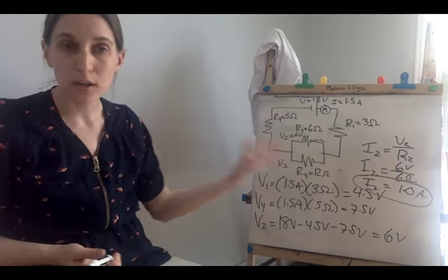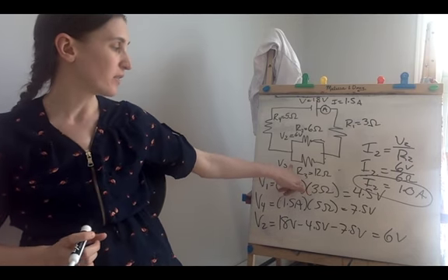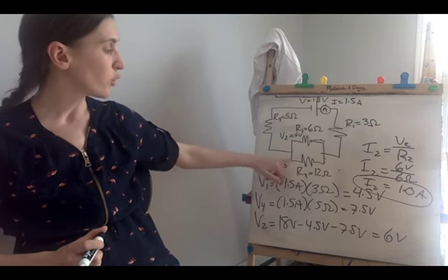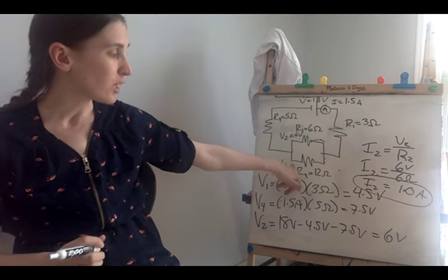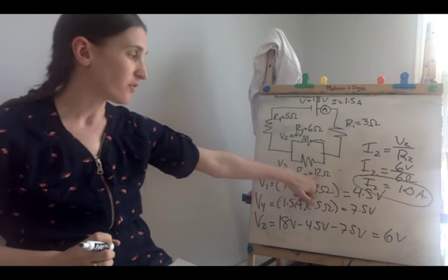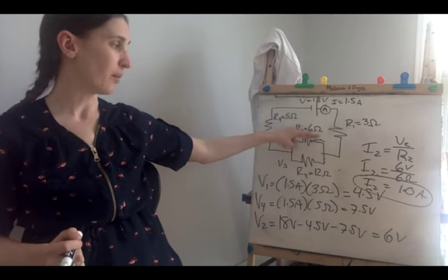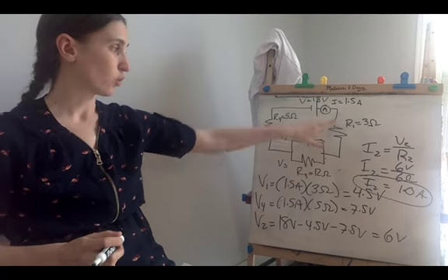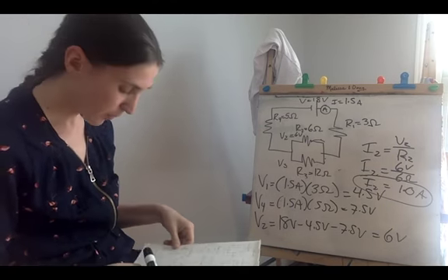And then you could, if you wanted to, explore something similar here, knowing, okay, the voltage would have been the same at V3 as it was at V2 because these are in parallel. So your voltage here also would have been 6 volts, and the current passing through here would have been 6 volts divided by 12 ohms, which gives you 0.5 amps, and you'll notice that, again, the sum of 1 plus 0.5 amps ends up equaling your total current of 1.5 amps. Okay? So that was part C.